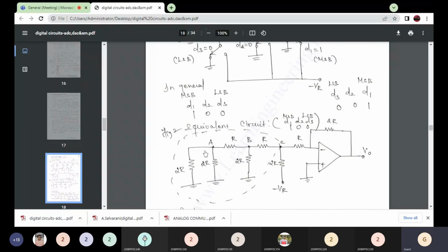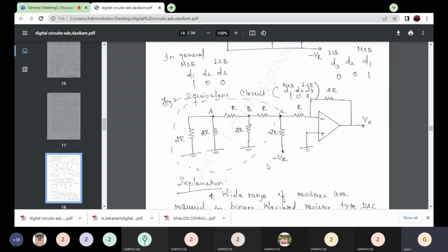So now we are going to simplify that, right? That is, we have to find the resistance value for this circuit. So anyway, just analyze that. Here is the 2R. 2R and R, these two resistances are connected in parallel, right? This is connected in series with this resistance, right? This one is connected in parallel with this resistance, right? These are connected in series.